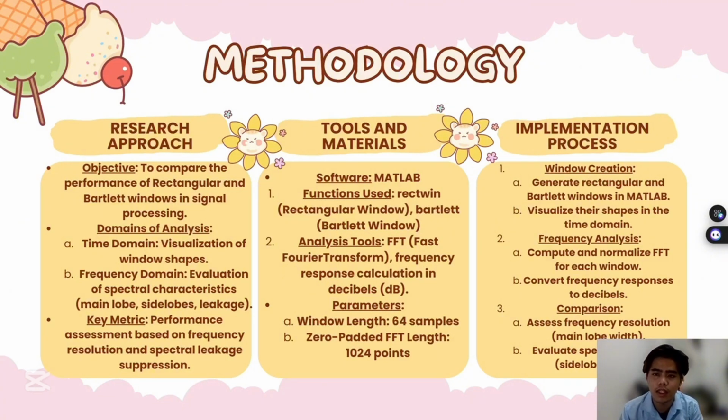Lastly is the implementation process. First we have the window creation. For the window creation, we generate the rectangular and the Bartlett windows in the MATLAB software, and we visualize the shapes in the time domain.